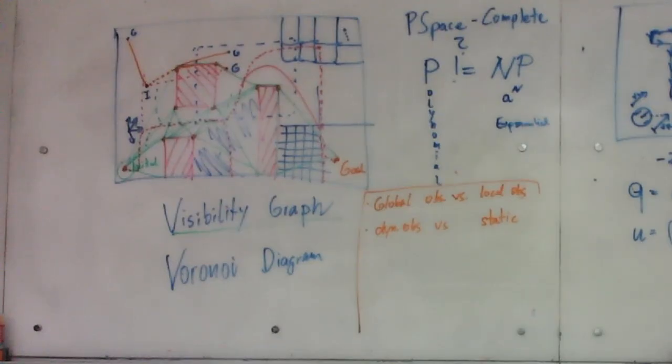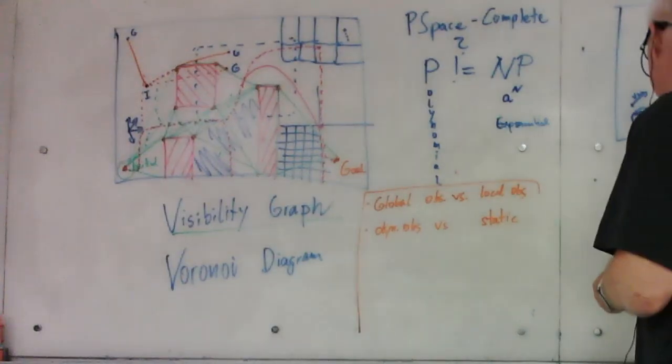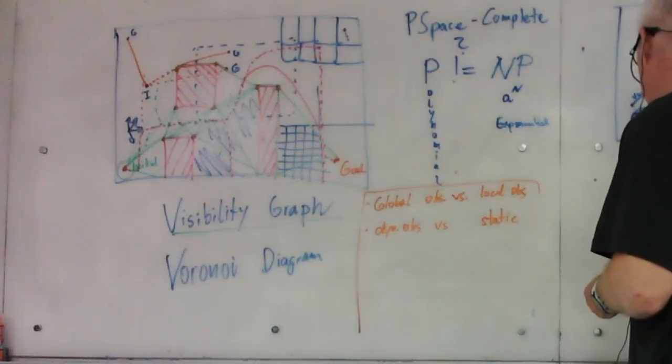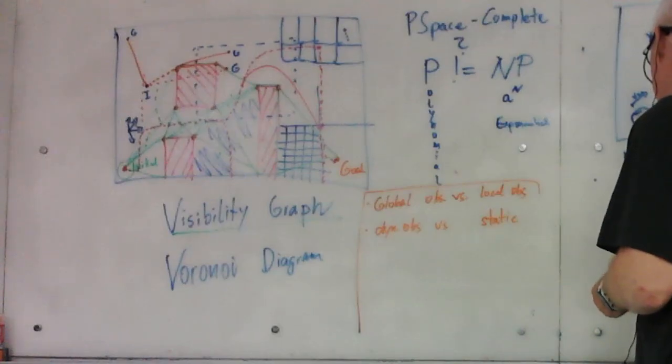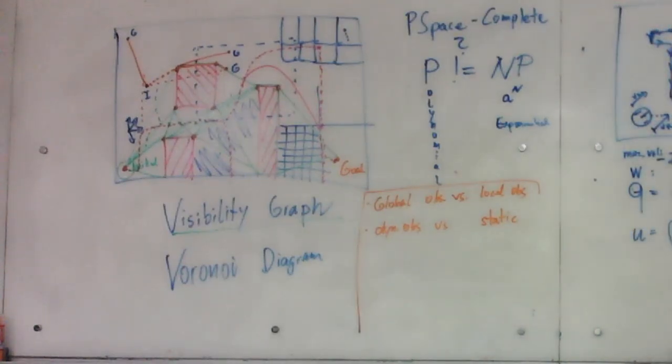Now, this is a parameter that we haven't set before, but that's basically the wheelbase, the distance between the two wheels. It would be the max velocity, and the wheelbase, let's make it 15 centimeters, 0.15 meters.